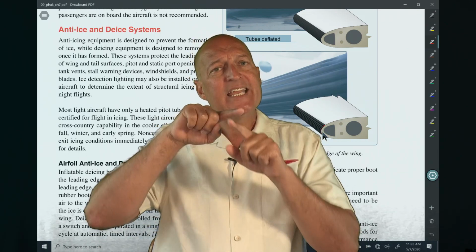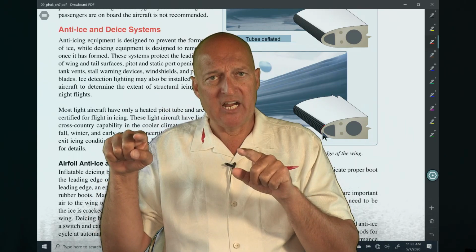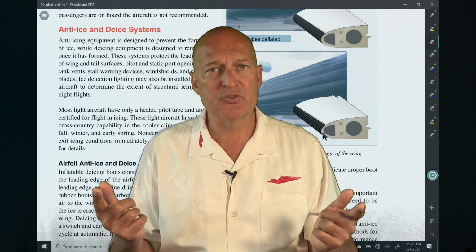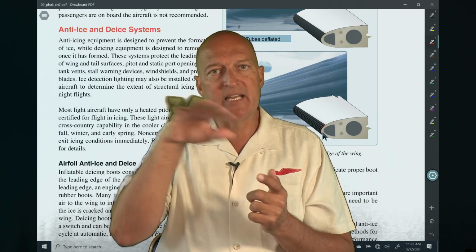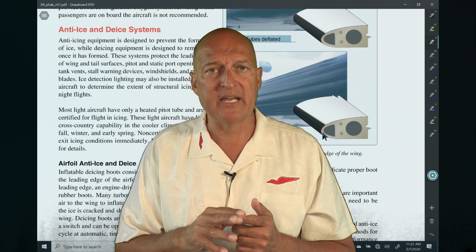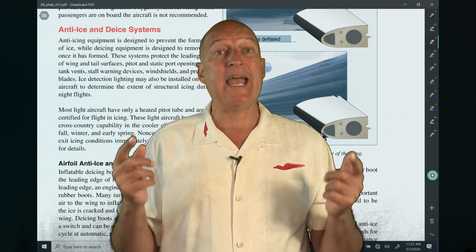What that does, it changes the shape of the airfoil of your wing. Now your airplane is not going to fly like it used to because it's not getting the airflow that it needed across that cambered surface at the top of your airplane. The other thing that it does is that it adds weight.